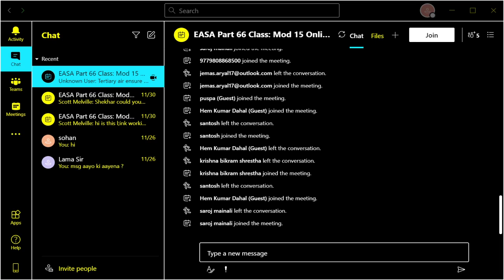These all get tested in what's called an Early Fail Detection Centre, or EFDC. Again, I used to work in one of these. We put the debris under a microscope initially to have a visual check, and then we put it into an electron microscope that goes right down into extreme detail, and it can actually diagnose and tell you exactly what that material is, what type of metal. Is it metal from the bearing itself? Is it metal from the bearing cage? Is it metal from the housing?